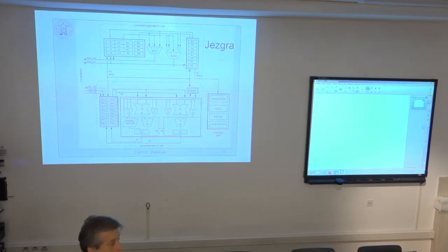And that is useful again exactly for implementation of the butterfly in fast Fourier transform implementation, because for one branch you have to add two arguments, for another branch you have to subtract two arguments. And if you can do this in a single instruction, it is the best way. I have two arguments, here they are added together, here they are subtracted, one from the other. Okay? But I cannot have multiplication in one and addition in another one.